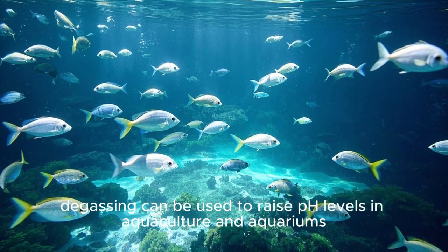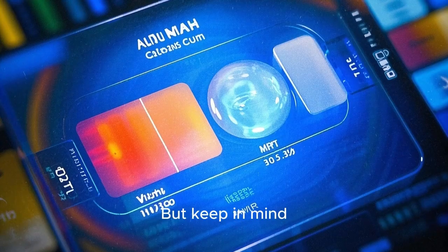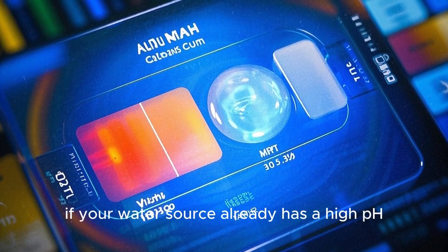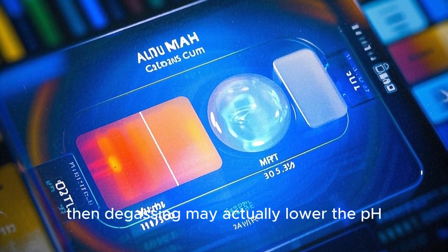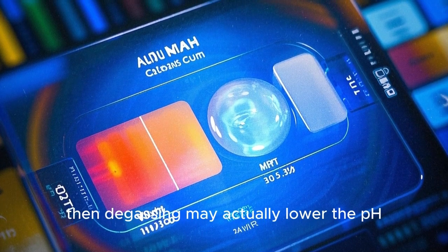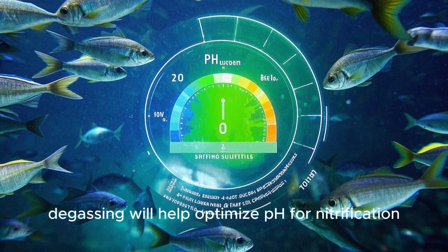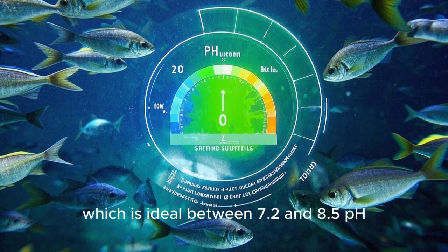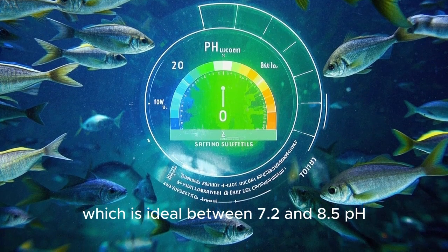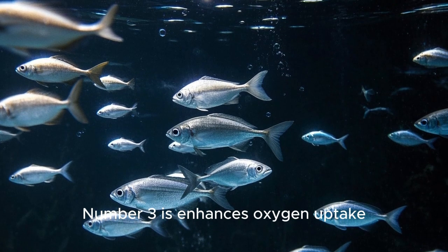Therefore, degassing can be used to raise pH levels in aquaculture and aquariums. But keep in mind, if your water source already has a high pH, like an alkaline well, then degassing may actually lower the pH. In most cases, though, degassing will help optimize pH for nitrification, which is ideal between 7.2 and 8.5 pH. Number 3 is enhances oxygen uptake.